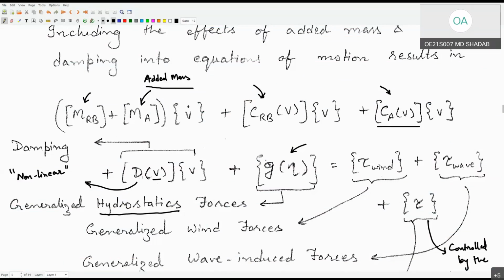They can definitely change. But here our objective is mostly surge, sway, and yaw for surface vessels. When we're dealing with surface vessels, they're still going to be floating, isn't it? And we will not typically be changing the ballast during the operation, or at least that will not be the significant portion of what we want to figure out. We want to ensure that our vessel stays in some position and stays in some orientation.